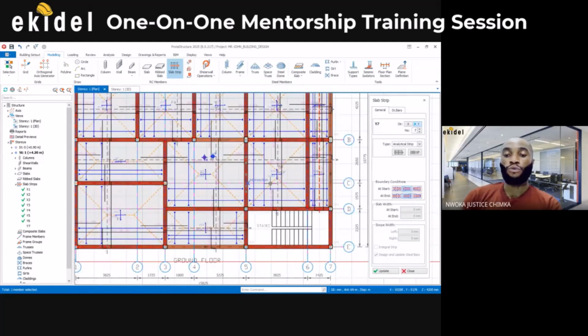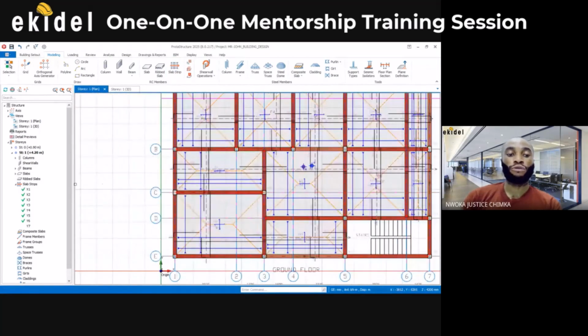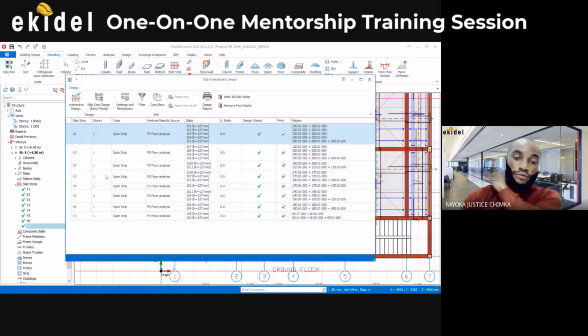Although now we are done cutting the whole slab strip, you can then choose to close, and then go and look at the slab design reports by coming to under the strip here. I'll click on the slab, right click here, and then you see here slab analysis and design. I'll click on this now, and then I can choose to generate the reports.